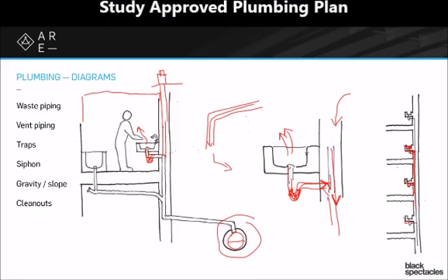That doesn't mean that each individual pipe goes up through the roof. They usually gather together and collect up, and then only a few pipes go up through the roof, because it's always a bad idea to have a lot of holes in your roof. So you want to have as few of those vent pipes actually penetrating through as possible. And so you often end up with kind of intriguing looking diagrams that have multiple elements coming all through, and they're all venting upwards until they get to that roof element.